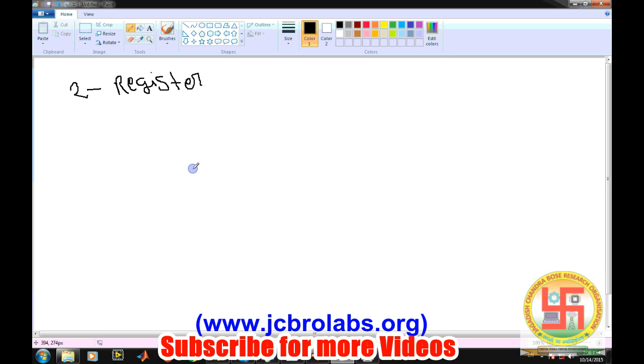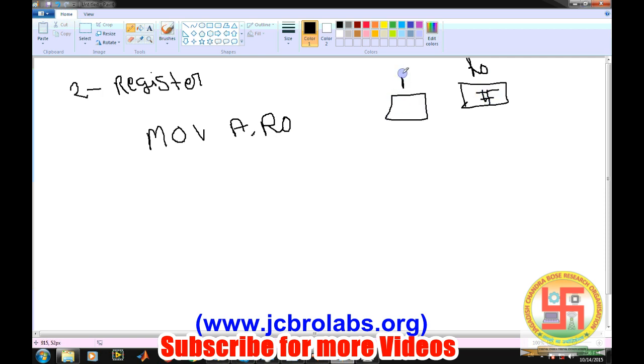In register addressing mode, both of the operands need to be registers, like MOV A, R0. Whatever the content of R0 is will be transferred to the accumulator. So by this instruction, the content of register R0 will go into the accumulator. In this case, both the operands are registers, so it is known as the register addressing mode.